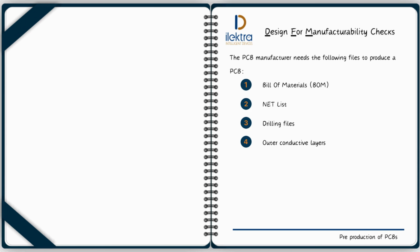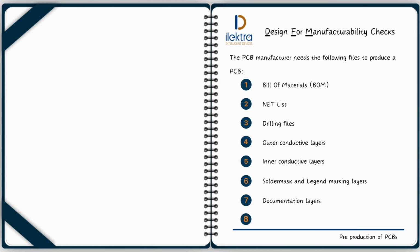Outer conductive layers with copper geometries like tracks and pads. Inner conductive layers with each layer's copper patterns. Solder mask and legend marking layers, sometimes called masking layers. Documentation layers with information on the details for finishes, tolerances and other requirements. Mechanical drawings regarding internal cutouts, slots and board outlines.